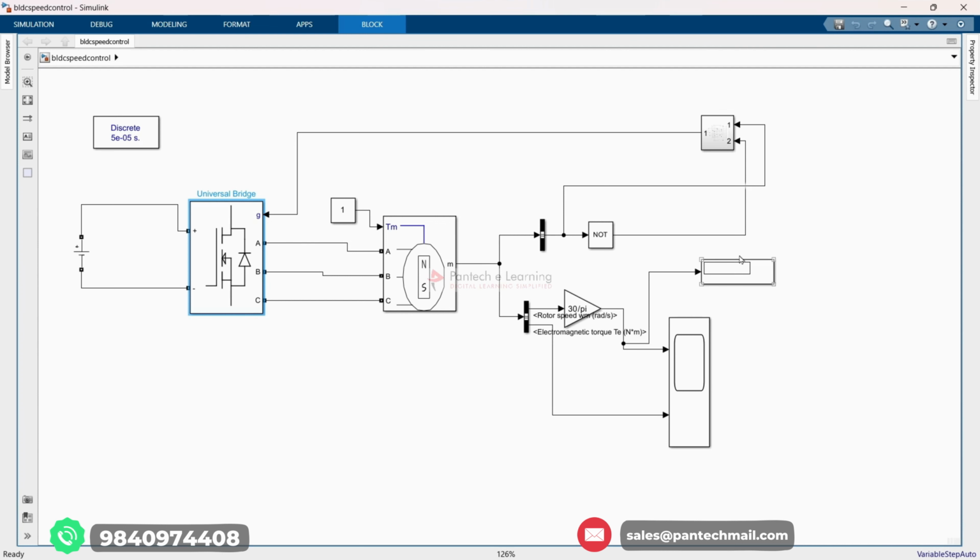in a detailed manner. So here there are 3 Hall effect sensors placed at equal angular distance around the stator part of the brushless DC motor. These sensors are mainly used to detect the rotor's position, that means the position of the rotor's permanent magnets, and determine which phase winding is currently in the most favorable position for energizing. So this is the main thing in speed control of a brushless DC motor.